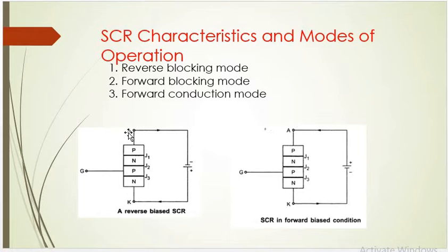So first, the SCR. The SCR has three terminals: anode, cathode and gate terminals. So how is it going to operate? It is a 4-layer device, that is PNPN.